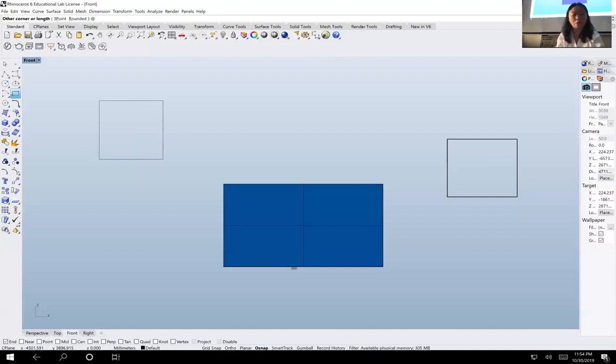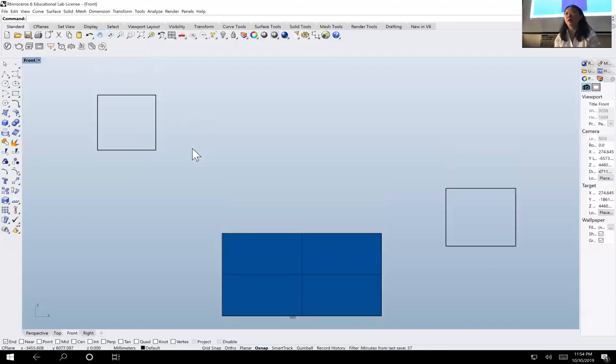So I'm going to do 2000, comma, another 2000. Press Enter, then you will see. I think horizontal first, because this one is 2400 by 2100. You will see the 2400 is in this direction. So the first number is horizontal.